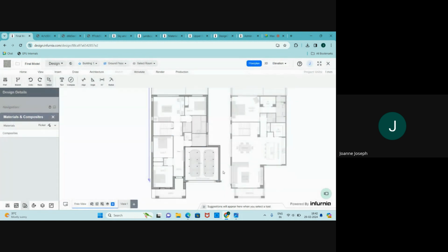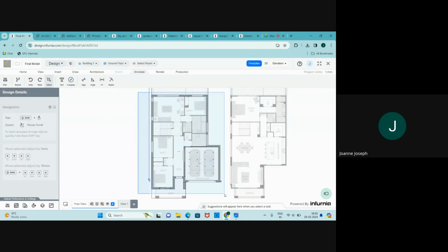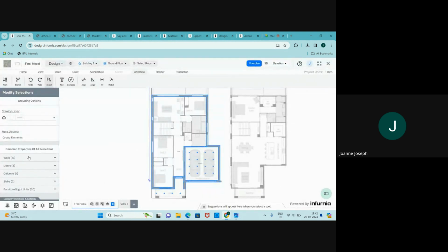Select apply. Now to assign this material to the wall, you can window select all of this, go to wall thickness slash composites, and select composite here, and now we have this new layer that has been placed in here.